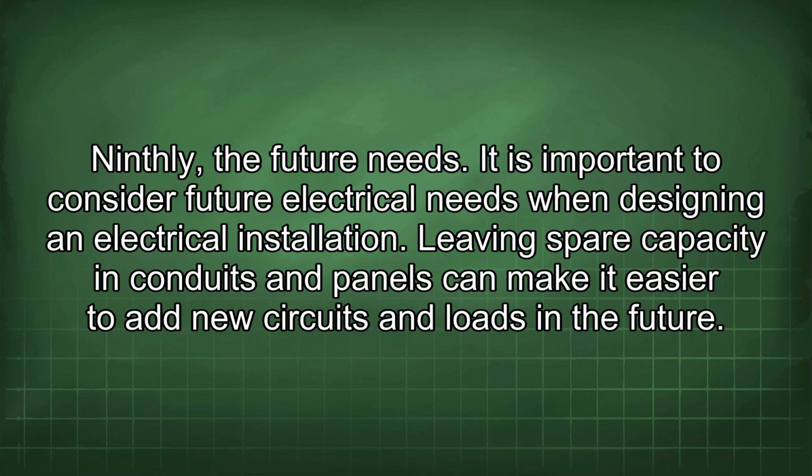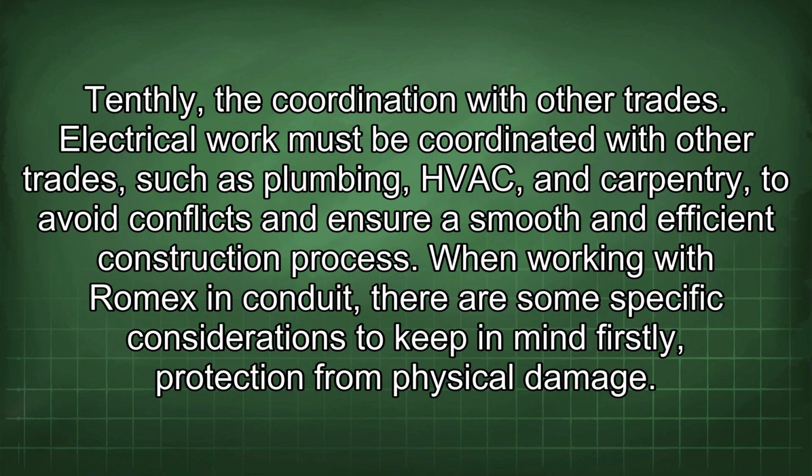Ninthly, the future needs. It is important to consider future electrical needs when designing an electrical installation. Leaving spare capacity in conduits and panels can make it easier to add new circuits and loads in the future. Tenthly, the coordination with other trades. Electrical work must be coordinated with other trades such as plumbing, HVAC, and carpentry to avoid conflicts and ensure a smooth and efficient construction process.